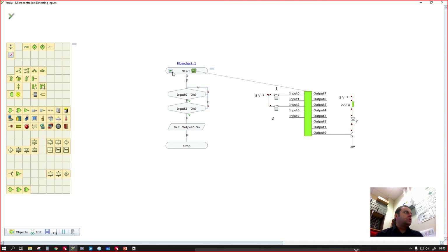Yeah, so now that won't happen. So 1 on, 1 off, 2 on, the light doesn't come on. It'll only come on both on at the same time. Now don't be wrong, it is possible to fake it, but you'd need to be faster than 4 microseconds, and you're not going to be faster than 4 microseconds. So that's AND control. The other most obvious logic control that we use, or the most common, is OR control.